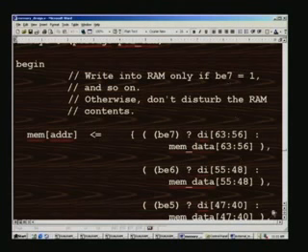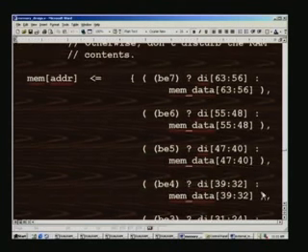And now to write this, what we need is the address. So the address is the write address, because R and W selects B7 only when it is in write mode. So evidently this address is a write address, WA. So the memory write address is going to be affected by these contents. What are the contents? We are going to write into this memory. So this is what we are trying to do. This is a PCI write, right?